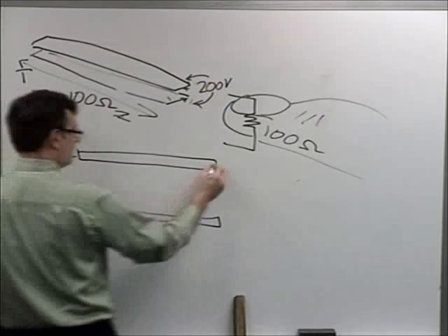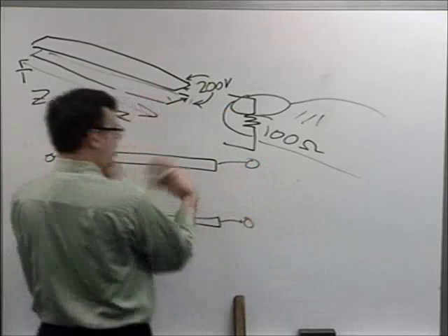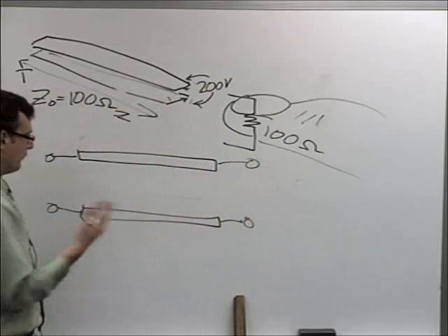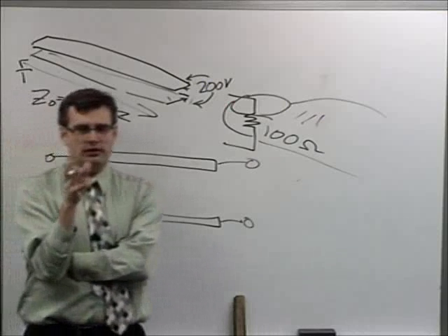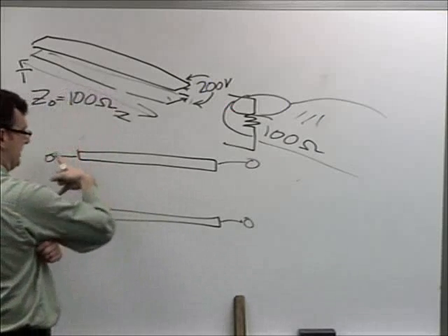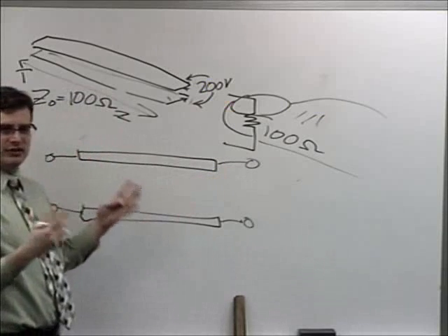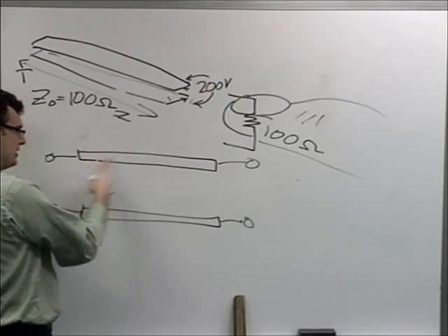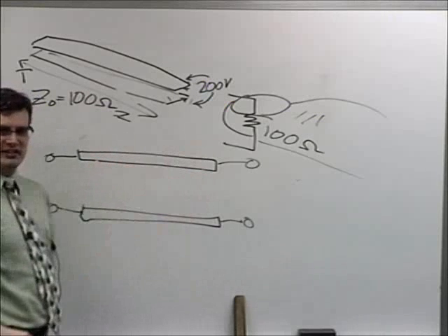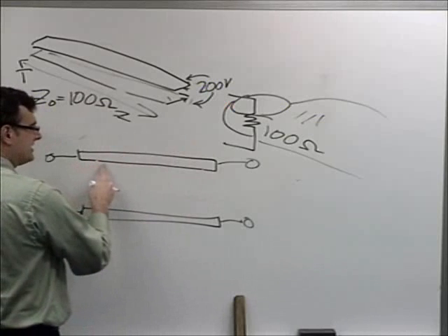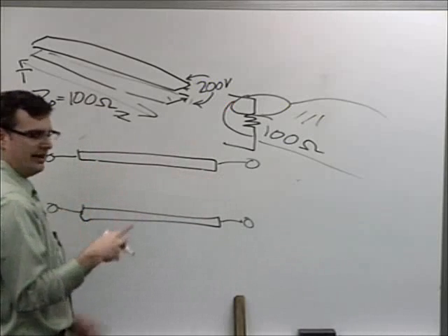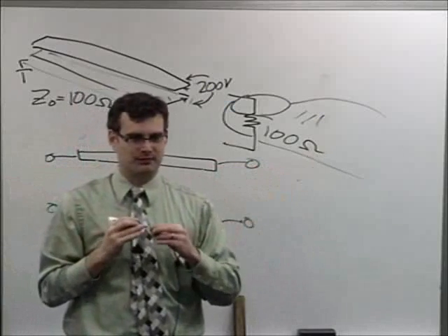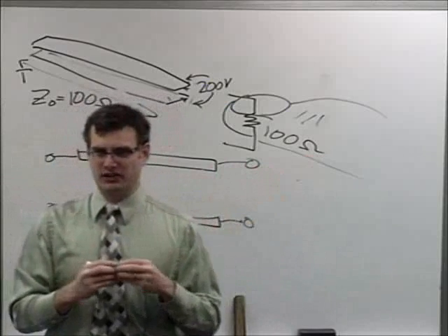As always, there are multiple ways to parse the mathematical solution of what's going on in this transmission line. If, for example, you say, oh, there are 200 volts DC static across that line, you can say I take my oscilloscope on that long, skinny capacitor. I put it here, here, here, here. Assuming I've got near infinite impedance, I will observe 200 volts static across there. Static. It's not a function of space, not a function of time. Constant 200 volts.